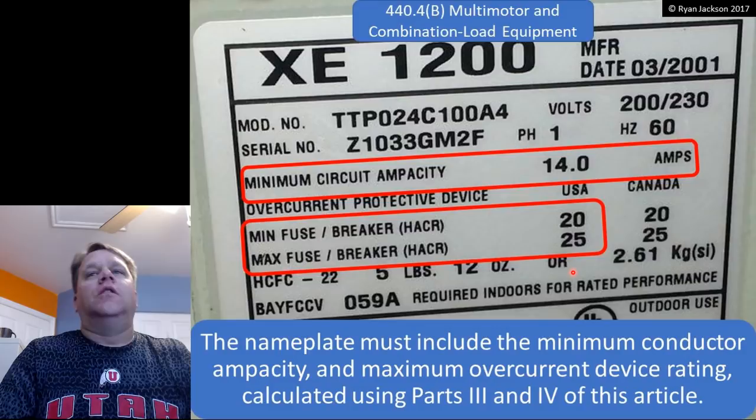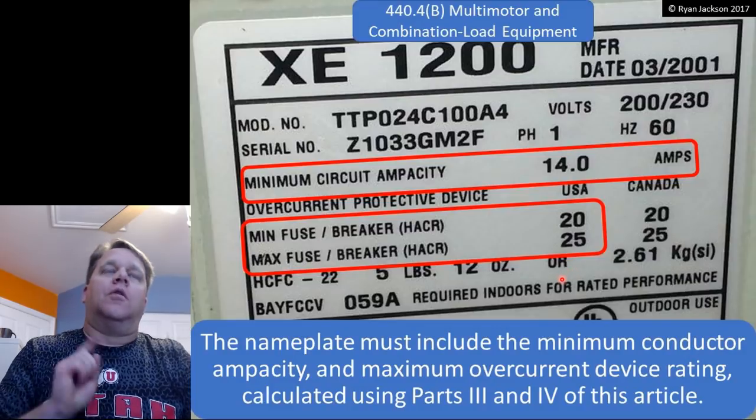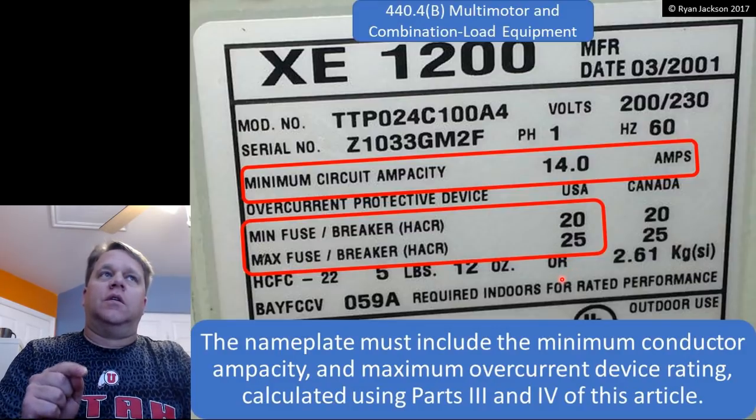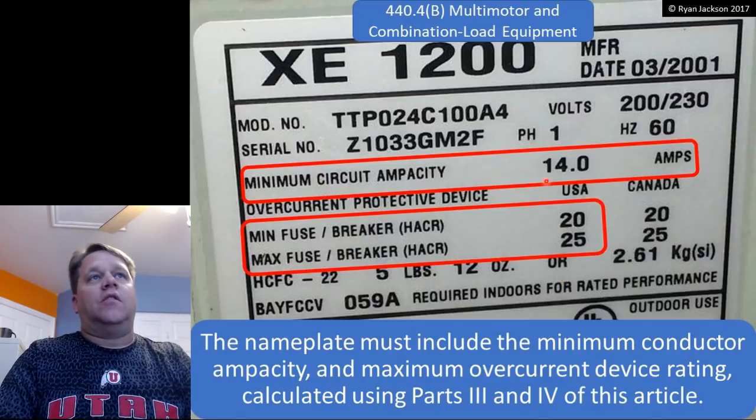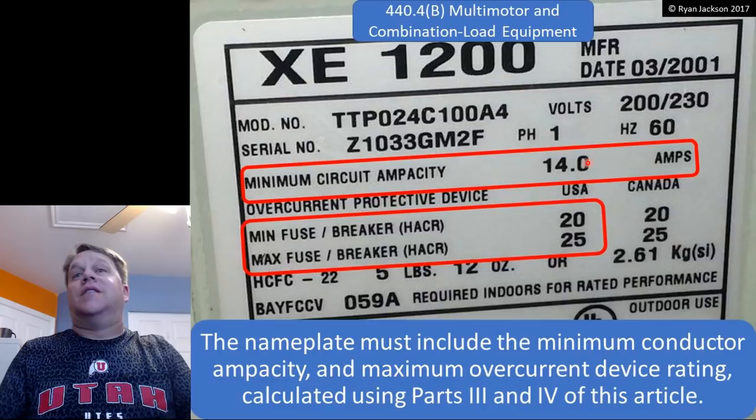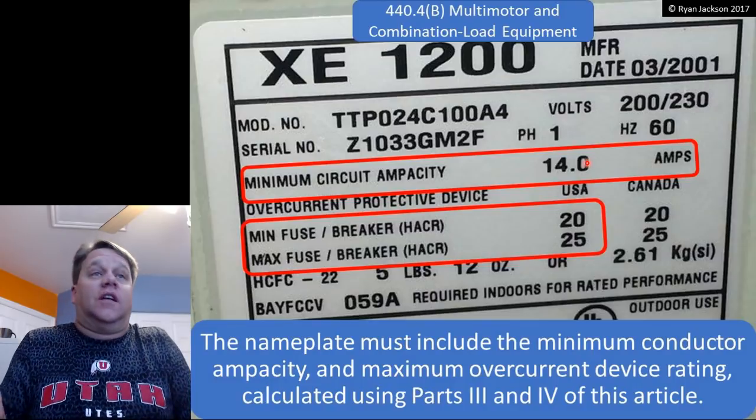The motor will shut itself off. The motor has built-in overload protection. The motor will not continue to run at greater than about 14.9, 15 amps. It will just shut itself off.